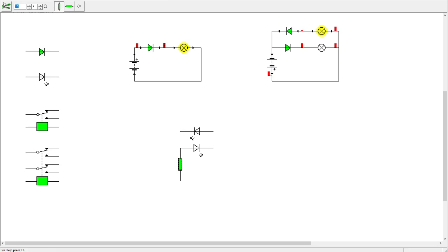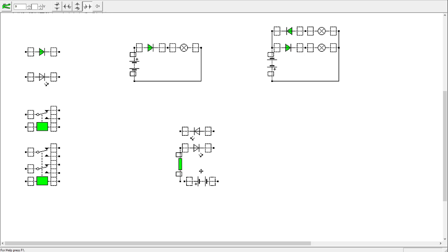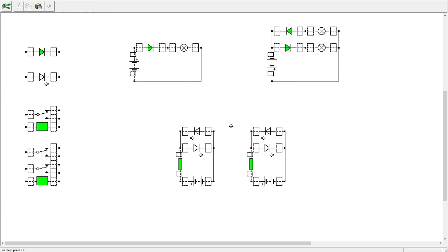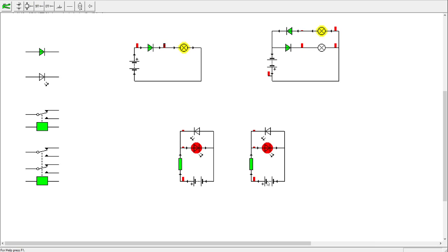We have to use a resistance of 500 ohms, or at least that's the resistance we will need if we use a 9 volts battery. So we can see that the lower LED can work, while if we do the same but with the battery the other way, it will be the upper one.